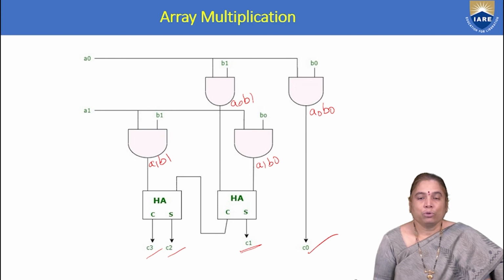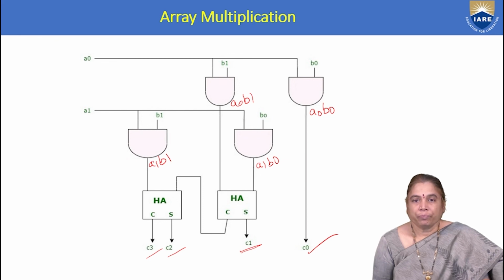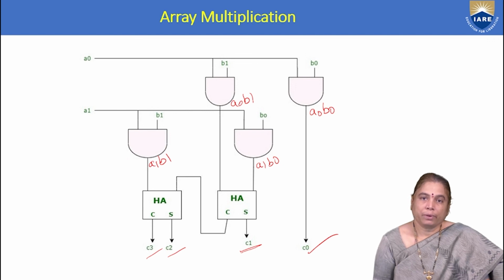And here, to preserve the weight value, the arithmetic shift right operation is performed in the process of multiplication. The signs are preserved in the Booth's multiplication algorithm. It checks 2 digits, Q0 and Q1, and depending upon the various combinations, it performs either the addition or subtraction with 2's complement, or the arithmetic shift right operation.